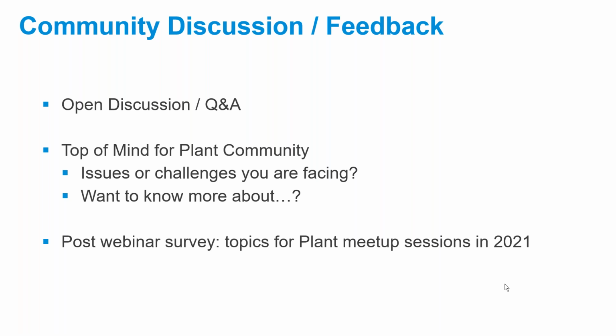I know that I've worked a lot with customers, and we actually have consultants out there that work with customers and help a lot with the ISO config tweaking and customization to get your annotations cleaned up, because sometimes it's really as simple as modifying a text style or some of your offsets and your leader styles in your dimensions and leaders that all of a sudden allow the algorithms used to generate the isometric annotations to work a lot smoother.